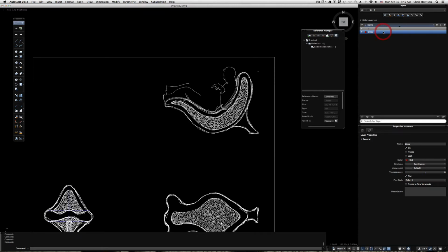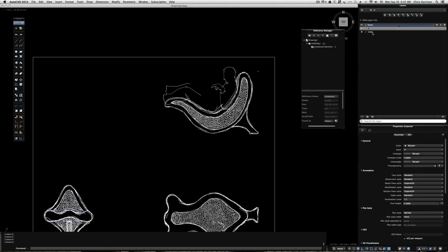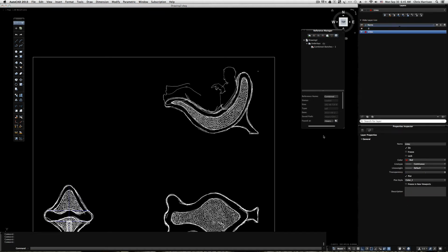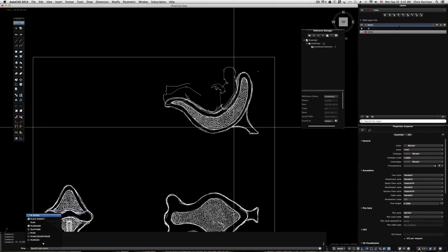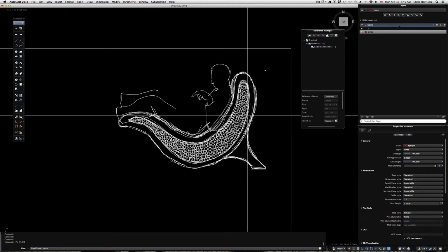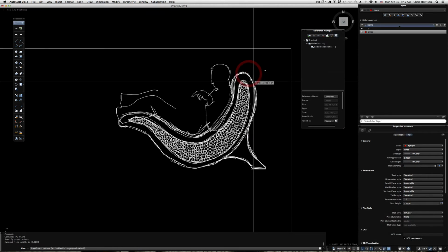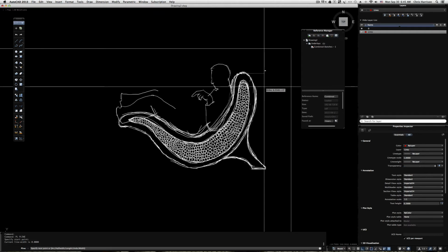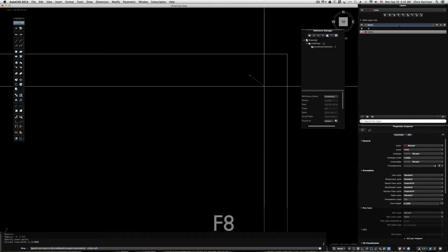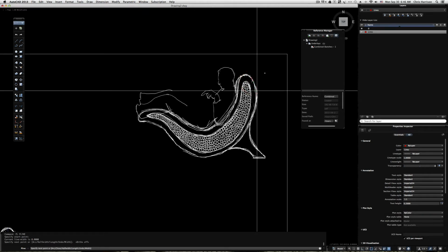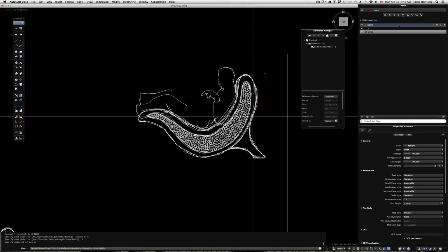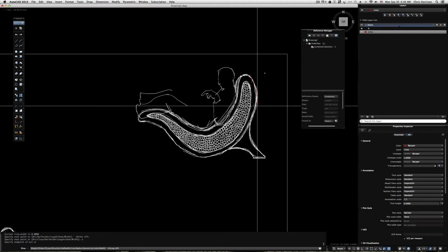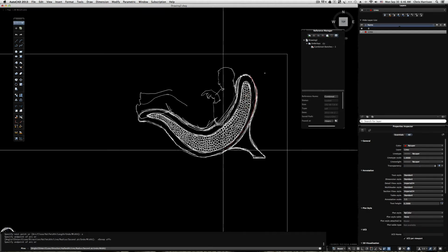So I'm creating a lines layer, and I'm going to double click on it to make sure that it's current, and I'm going to type in PL for Polyline, and what I'm going to do is begin to trace this shape. I'm not worrying about scaling right now. I just want to trace this shape and get this outline clean. So I'm going to turn off my ortho and begin coming down here, and I'm going to hit A for arc because I want to be on the same line, and I'm going to go ahead and turn off my O snap as well. So I'm coming here, drawing down.